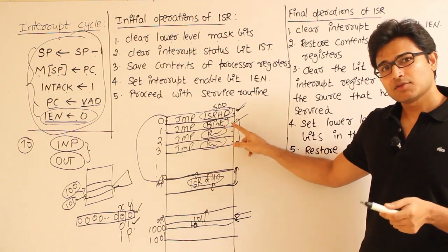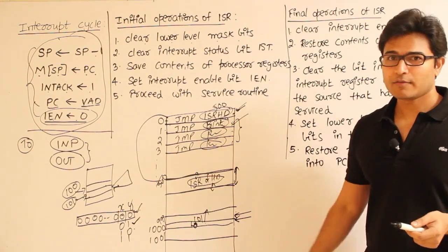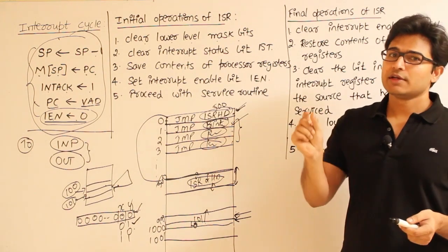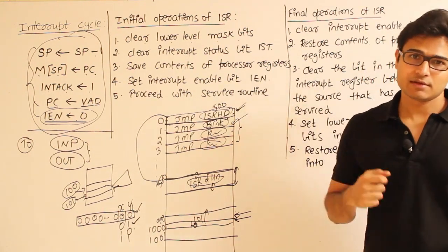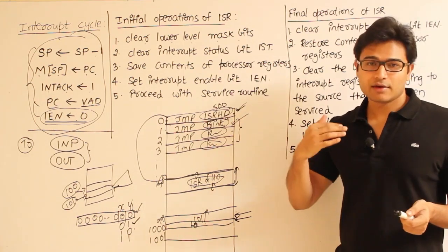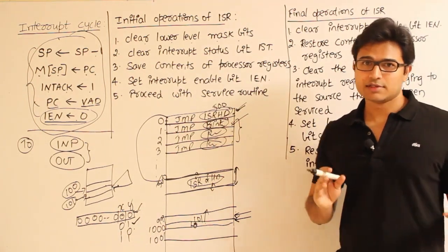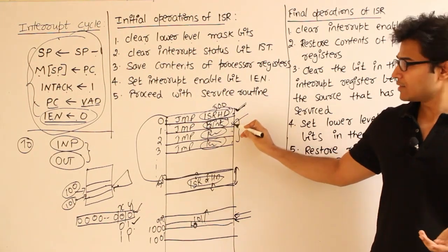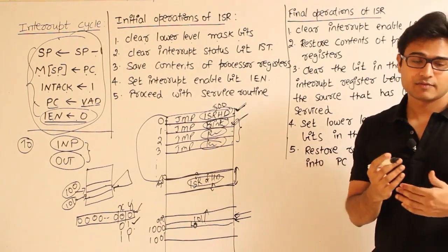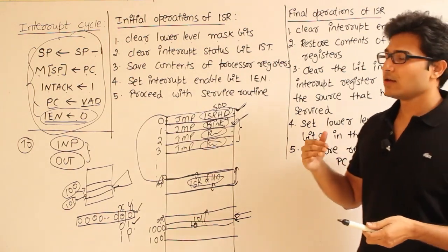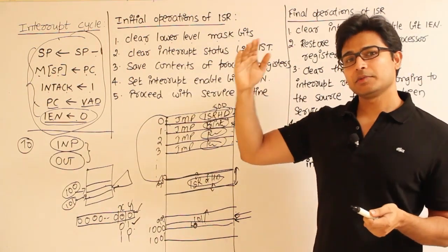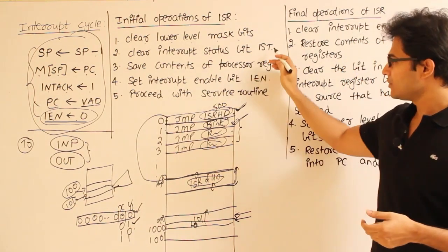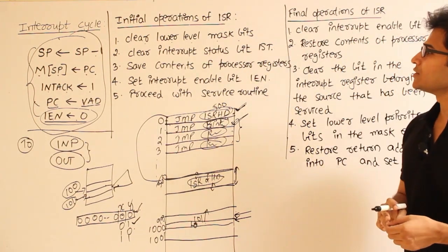It will not hurt the low speed device at all, because the high speed device requires only a small amount of time, but the low speed device will require a lot of time. You can think of it this way, maybe this one may take microseconds, this one will take milliseconds, like that. So that is why we always let the high speed device interrupt the low speed device, and that can be done by using these interrupt service bits.